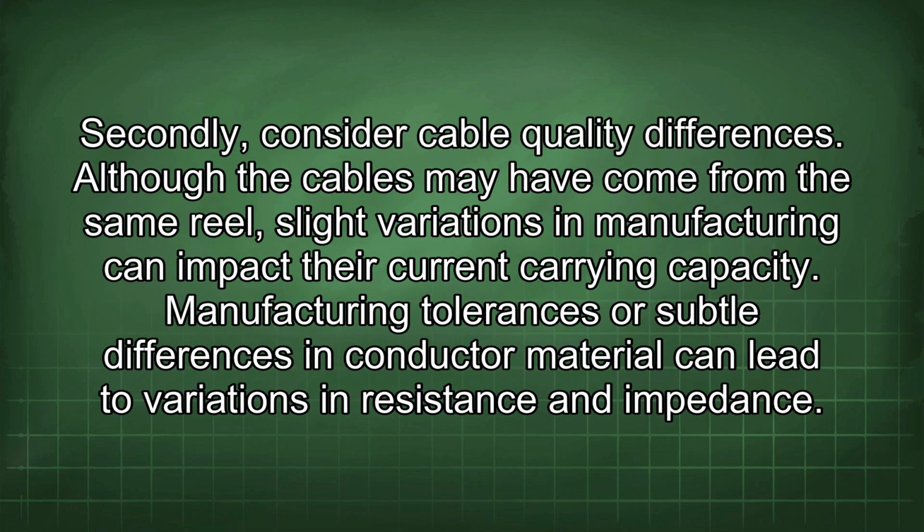Secondly, consider cable quality differences. Although the cables may have come from the same reel, slight variations in manufacturing can impact their current carrying capacity. Manufacturing tolerances or subtle differences in conductor material can lead to variations in resistance and impedance.